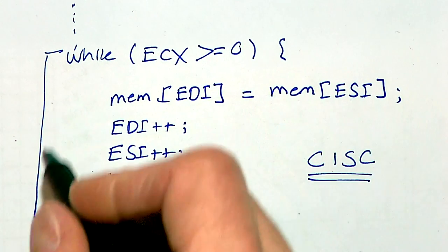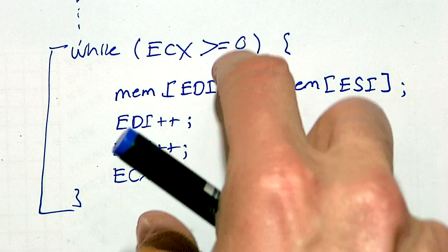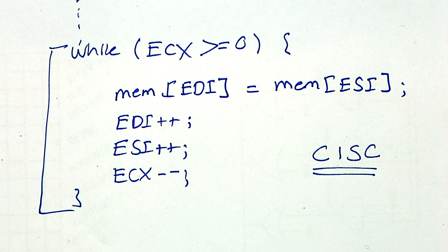So the way this is implemented in the Intel architecture, well, in the microarchitecture, is through microcode, which we will discuss a lot tomorrow. You go through a microsequencer that sequences through this little program, if you will. But this little program is a single instruction, really. It's not a program. It gets translated into micro-operations that you sequence through internally. And we will see that.